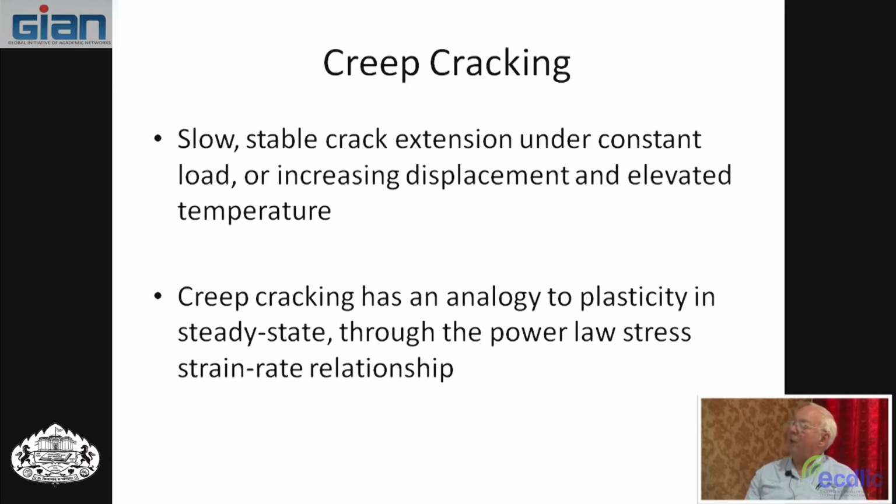But creep cracking is this. You get slow, stable crack extension under constant load or with increasing displacement at an elevated temperature. This is a little bit like environmentally enhanced cracking, only the environmentally enhanced cracking that we looked at was pretty fast.